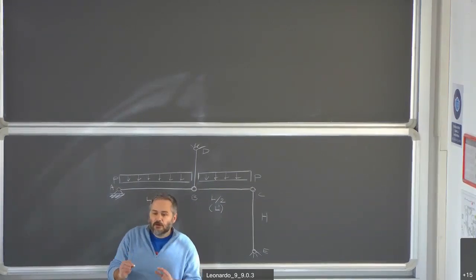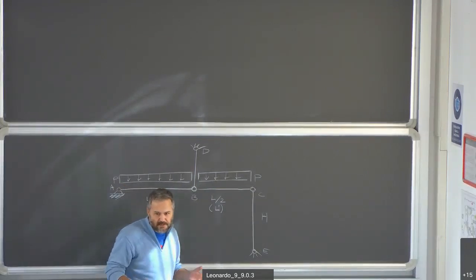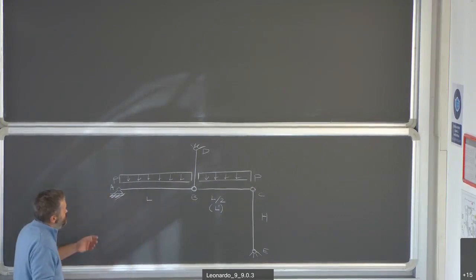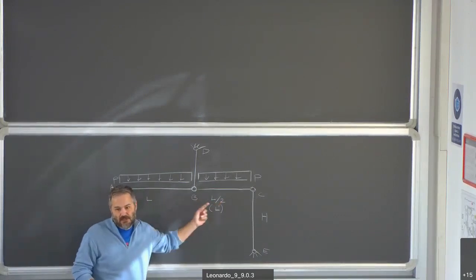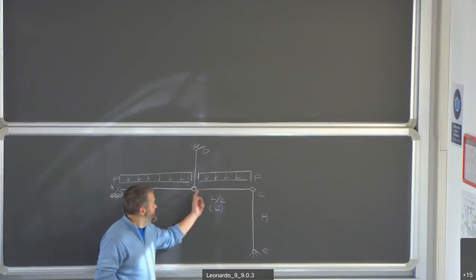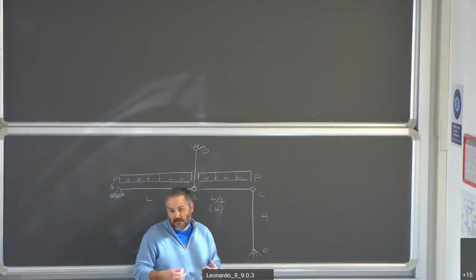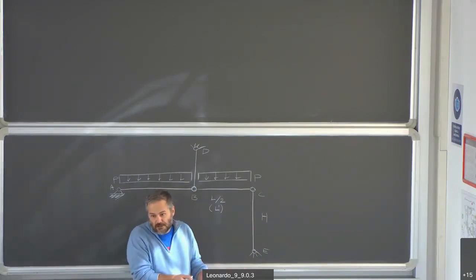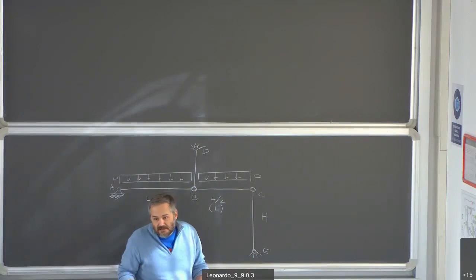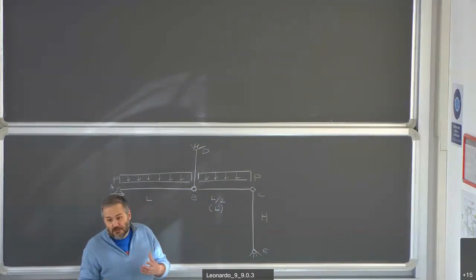Now, without performing any calculation, what should I expect? I should expect that horizontal members are subjected to bending moment and shear. A vertical member that is below a beam is likely to be subjected to compression. This is usually the case, unless you have very fancy and very strange load combinations.